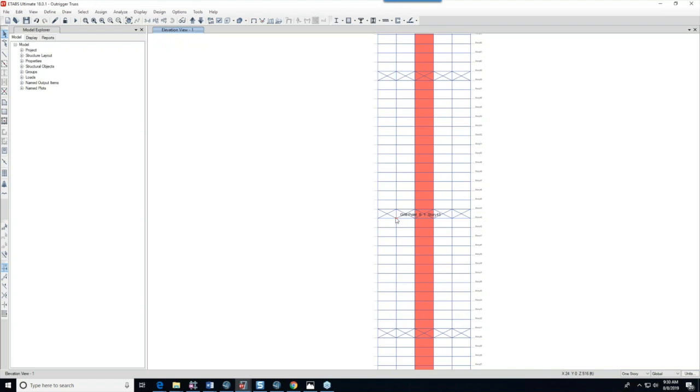Now, it may also not be suitable just to say, all right, I'll use a semi-rigid diaphragm. If you have an 8-inch concrete slab, you would also inhibit load going into the top and bottom chords of your truss. So there are times where engineers have to pay a little more attention to the load path and make sure that if you want 100% of the load to go into these elements, there aren't elements that are going to share or inhibit the load path to those elements.